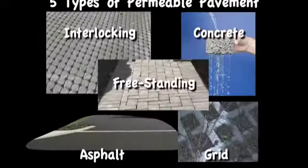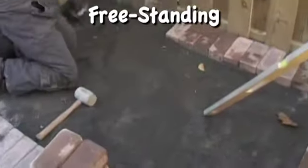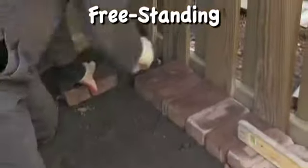There are 5 standard types of permeable pavers. The most basic type of paver uses freestanding bricks, concrete blocks, or flat stones laid on a bed of sand and stone aggregate. Of the pavers, freestanding are the least stable and are only recommended for infrequently traveled or light